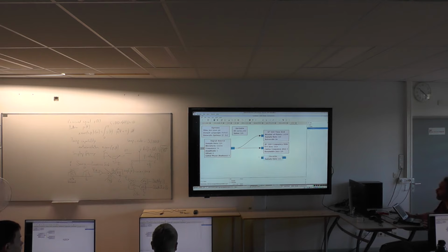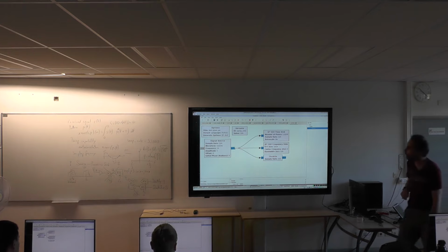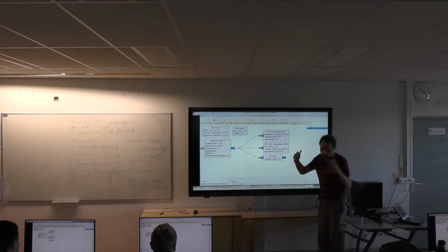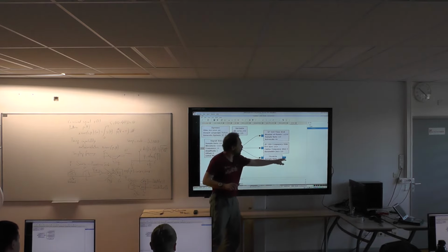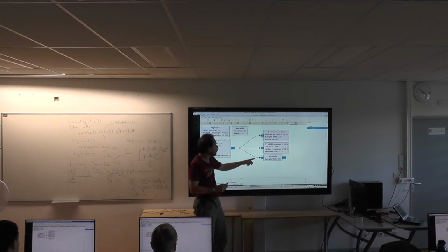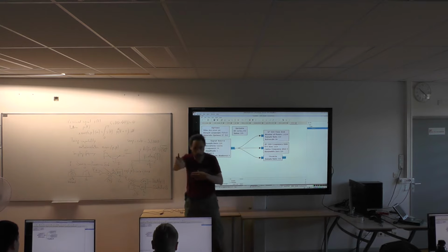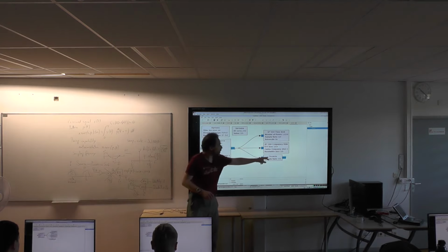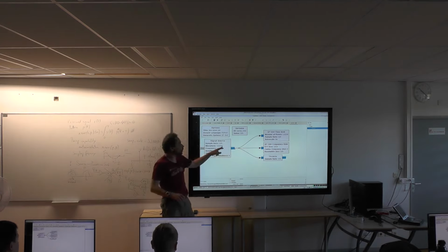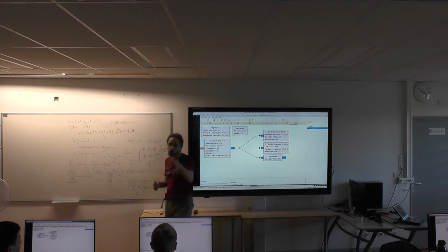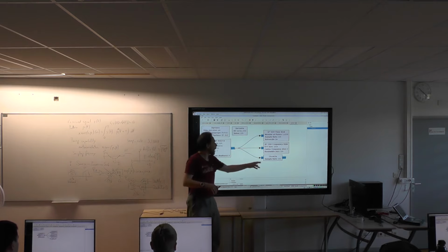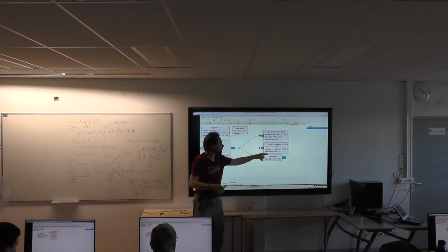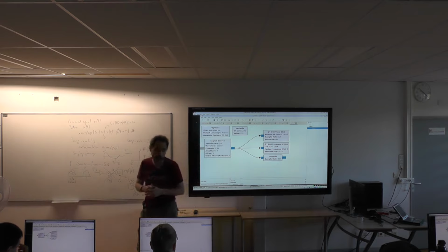And you just connect this guy in parallel to the others, despite there is an input and an output. It's documented in the GNU Radio tutorial that the throttle block does not need to have the output connected, and it's actually somewhat more efficient to just have an input and no output, so you don't have to stream the data. And actually the throttle block will backward tell the signal source, I received 32,000, now slow down, stop sending data for a second, and only 1 second later will the throttle block allow the source block to stream again a batch of data, and the other blocks will be somewhat scheduled by this throttle block.